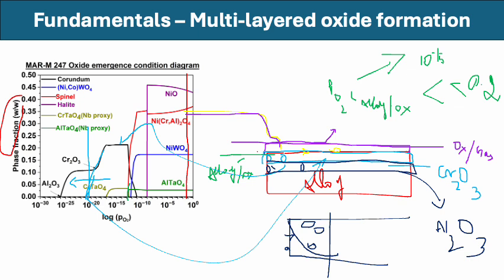surface, which means oxygen atoms, as I mentioned. The initial first stage in oxidation is that O2 comes to an adsorption site on the surface. There are several adsorption sites. If you look at a surface from the top view of a crystallographic plane, you will have crests and troughs. If you consider this ball model, there is an arrangement of atoms, and the FCC metal can look like the 111 plane might look.